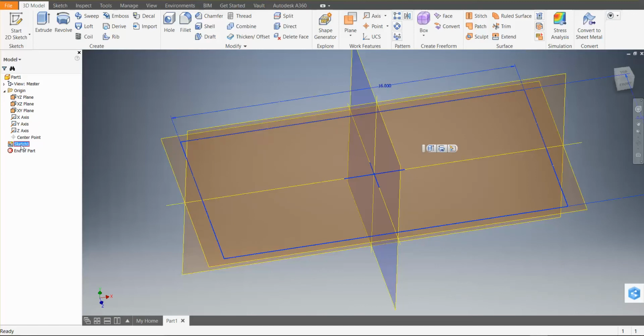You don't need to double click on the actual sketch when you're naming it, just hold down the mouse. What you're going to do is type in foundation. And that's the sketch for the foundation. Now we'll take this and we'll extrude this out.